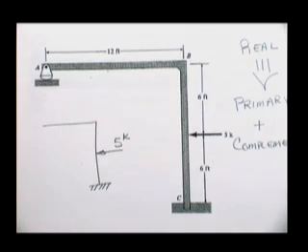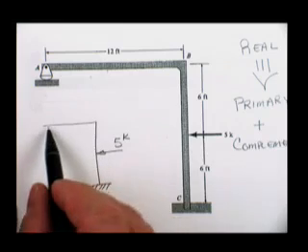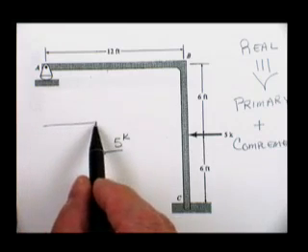Now you need some skill in drawing what the deflected shape looks like. And you don't have to be real smart at it, but the better you draw it, the easier the problem solution appears. There's nothing going on up here, so none of these pieces will be bent.